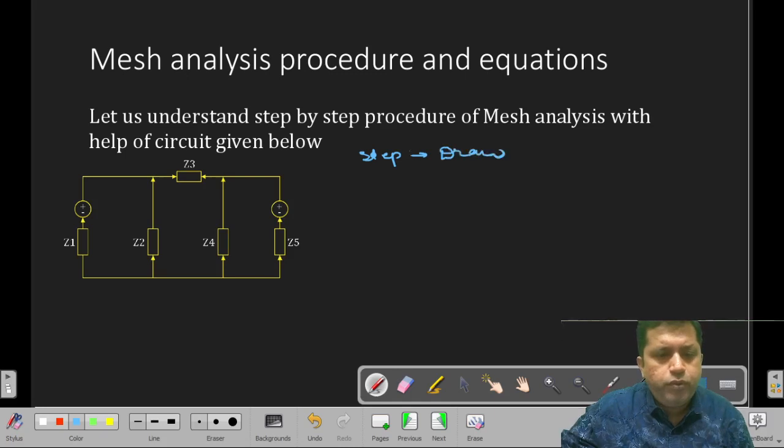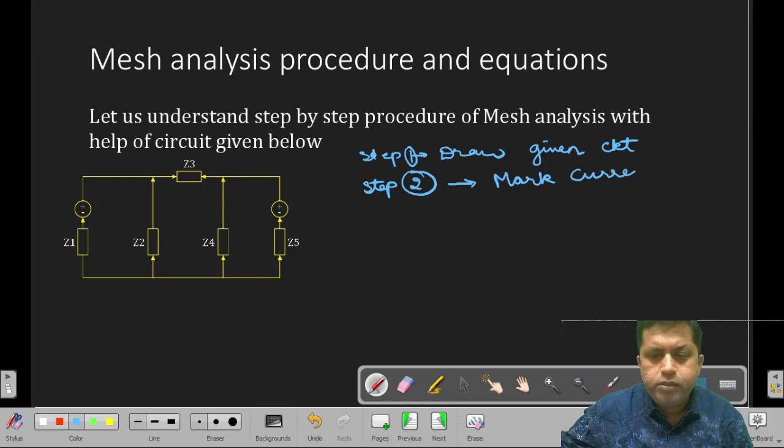Step 1, draw the given circuit. Step number 2, mark currents in any one direction.